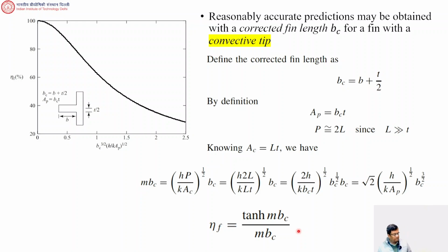Right, so we have done a few things about heat sink. So what have we done so far? We have essentially looked at rectangular fins. And for rectangular fins, we have considered natural convection as well as forced convection. And we have considered not only the fin equations, but we have also optimized the fin array. We have optimized a single fin, whereby we got that beta equal to 1.4192. We've been spending so much time on that.